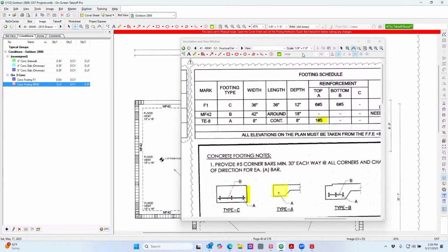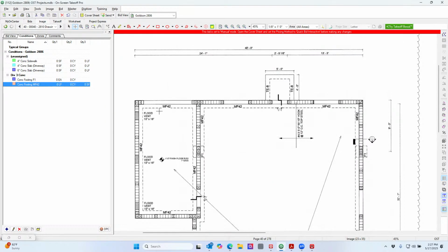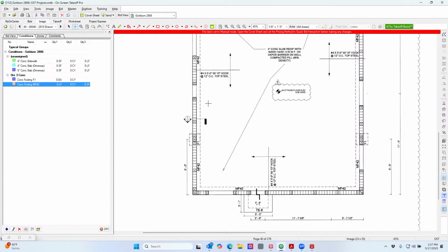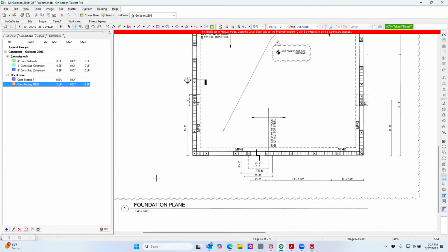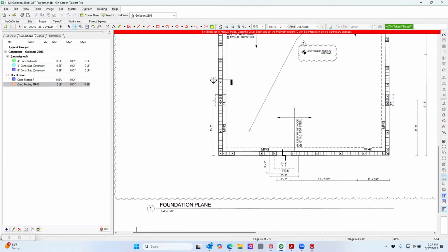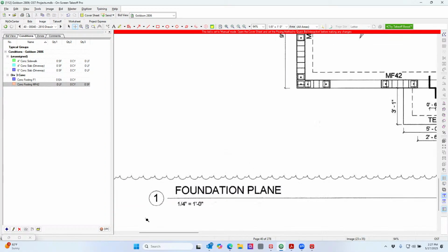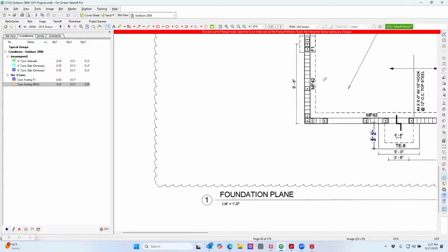So now let's shrink this. Now let's check the scale again. See, this one says a fourth. This is why you always have to check the scale, y'all. So let's check and see, I'm on an 1/8 scale. Let's see if it's a 4th. Yep. Boom. Always have to check your scale.